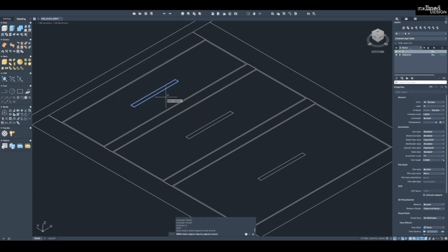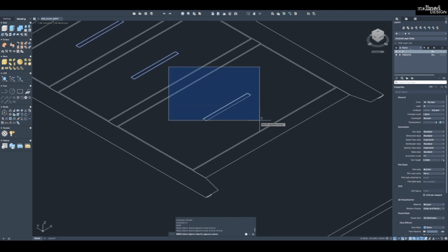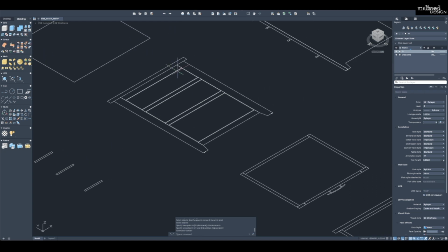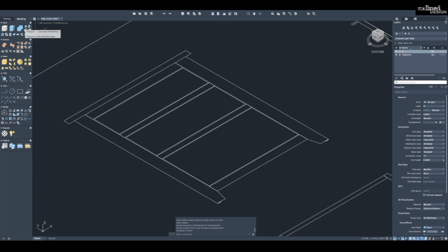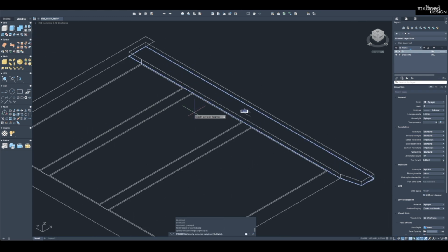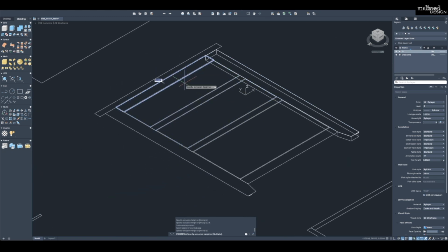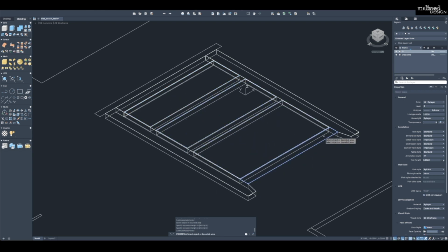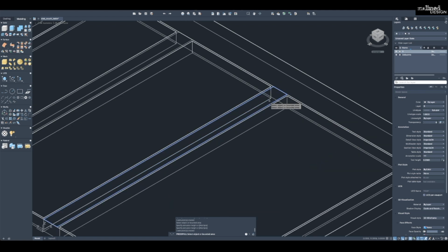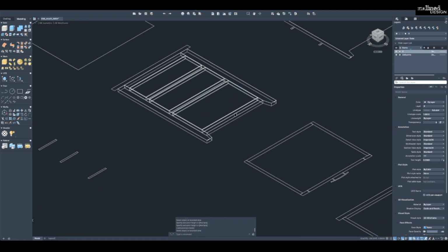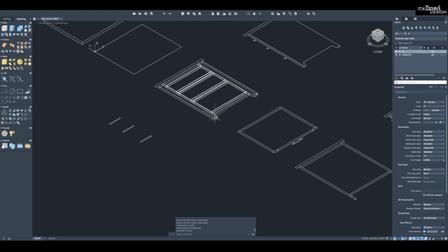You can do it a bunch of different ways, and I could make these as a solid object, but what I like to do is use the press pull command, and I know the thickness of all these faces. If you're buying standard lumber, it's going to be 3/4. So I'm just letting it pick the boundaries. I'm just going down by 3/4. I'll get these 2 middle rails as well. So you just want to make sure that the part that you want to press pull is highlighted in blue. So now I have those components all done.